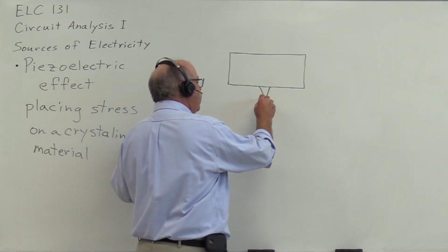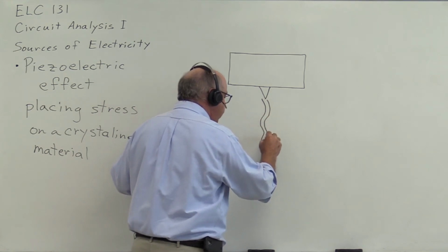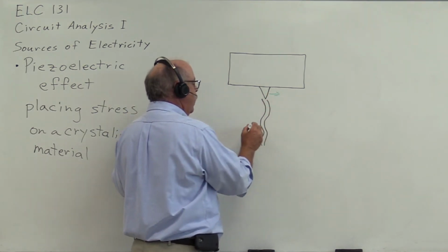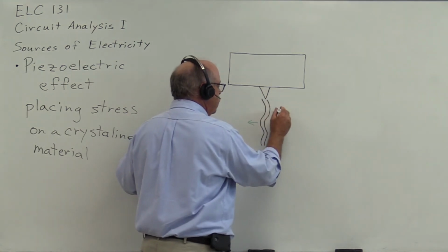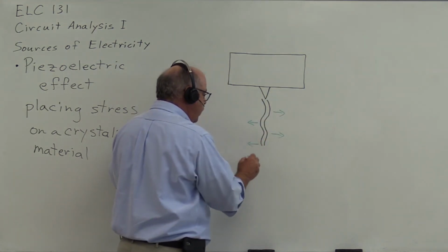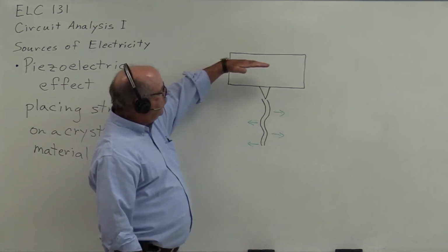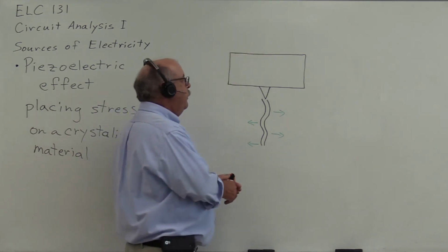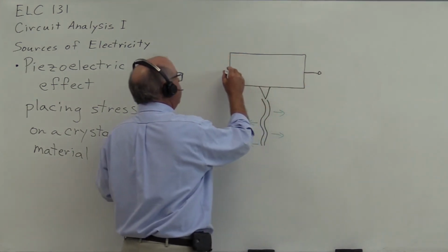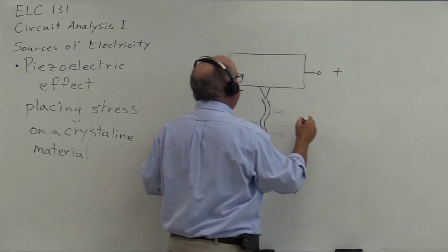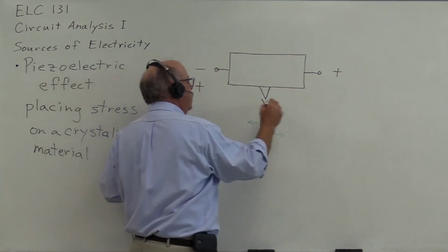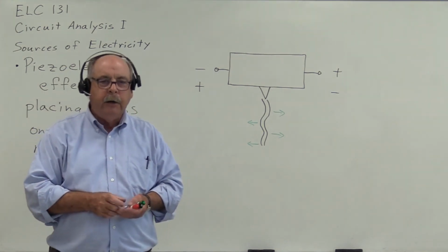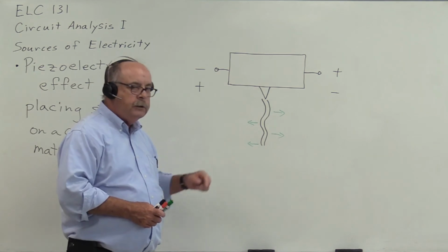And as the needle went through the tracks of the record, this caused the needle to move this way and move this way and move back this way and move back this way, causing this crystalline material to be twisted this way or this way or this way or this way, generating from the sides of the crystalline material a voltage that changed from positive to negative to positive, which would recreate the audio information that was used to create these tracks.